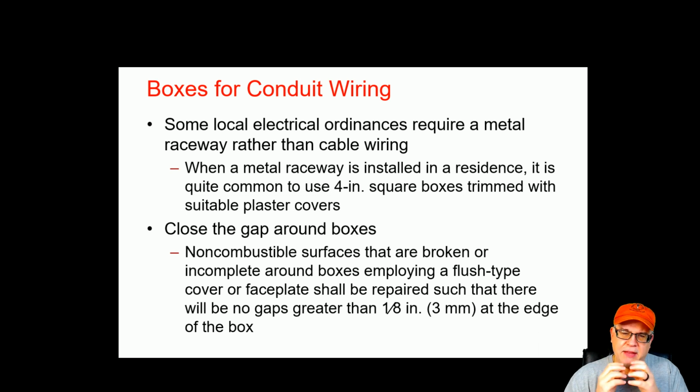Now, in this case, when I put those boxes in, or actually, to be honest with you, when I put any box in a wall, whether it's in gypsum board or not, I have to worry about the gapping or how deep that box is in the wall. Now, think of this. You've got to close the gap. Now, when you're an electrician, you put that box up, whether it's a 4-inch square or a nail-up box, you're relying on the drywaller who comes in and he's going to cut your openings.